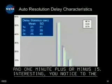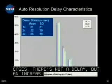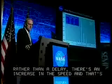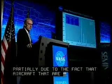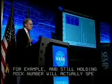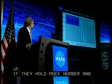Interesting, you notice that to the left of center, in some of the cases, there's not a delay, but an increase. Rather than delay, there's an increase in the speed, and that's partially due to the fact that aircraft that are descending, for example, and still holding Mach number will actually speed up. As they hold Mach number while they're descending, they will speed up and get to the end of the trajectory sooner.